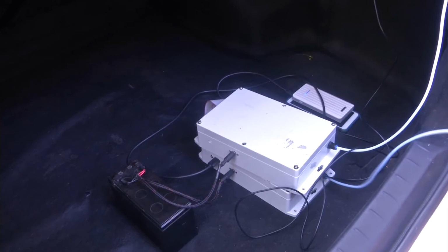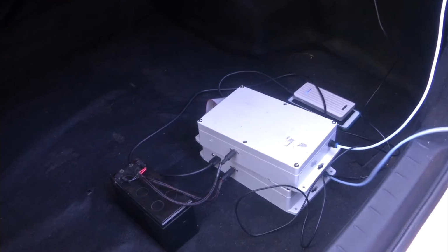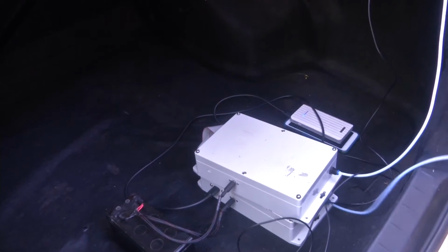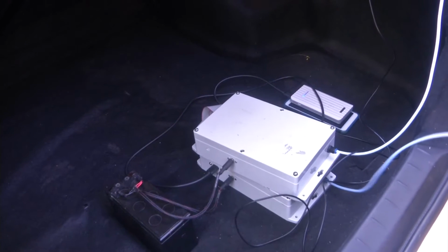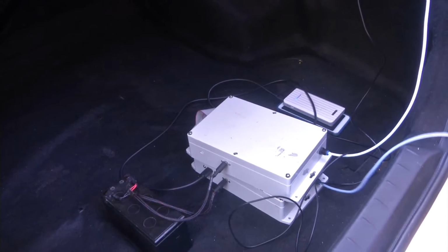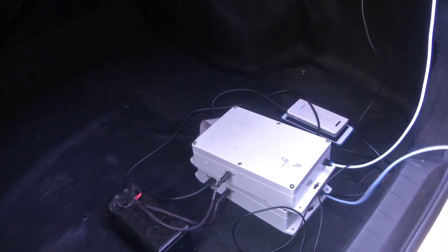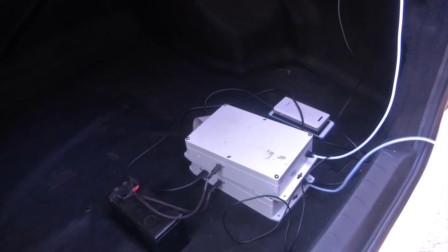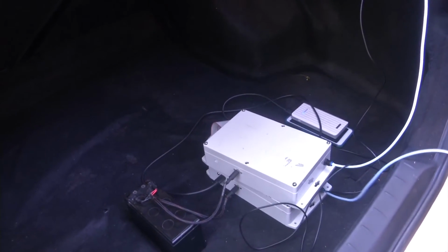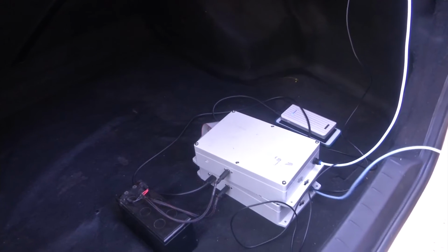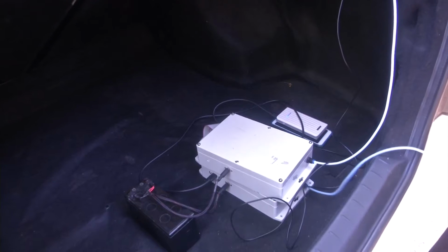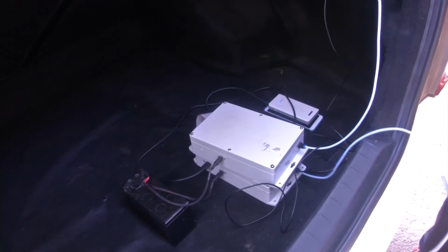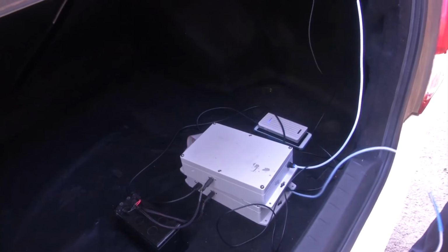Now what are the data items that we want to collect? It goes back to what I mentioned to you. From ambient we are getting NO2, nitrogen dioxide, nitric oxide, ozone, ammonia NH3, hydrocarbons, particulate matter 2.5 and particulate matter 10, all of them measured. For exhaust it is nitrogen dioxide, nitric oxide, ammonia, hydrocarbons, and particulate matter 2.5 and 10; ozone should be nil there. So these are the main pollutants.